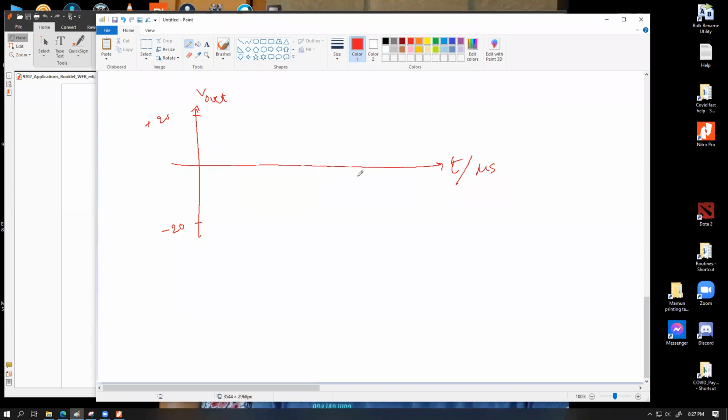Now, the slew rate information means that whenever the output changes, for every 10 volt variation of the output, a practical op amp would require 1 microsecond of time, which is sort of like an acceleration value for the op amp to handle. So let's say the input signal is changing with, let's say, 2 microseconds. So let's say this is a microsecond scale. Here is 1 microsecond, and here is 2 microseconds. Let's say the V in is undergoing some change.